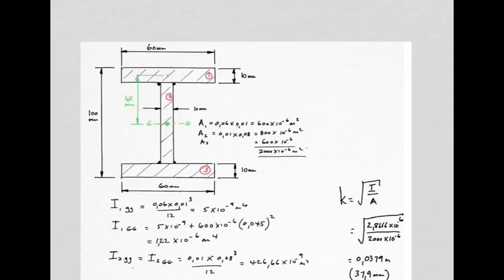Next step is to consider area 1, which is this rectangle as discussed, and determine its second moment of area about an axis passing horizontally through its own centroid. Now its own centroid is going to be denoted with lowercase g's like that. And remember, for a rectangular shape it is BD cubed over 12. Breadth times depth cubed over 12. An easy way to remember it is B is this way in line with the axis that you're dealing with, and D, the one that gets cubed, is perpendicular to the axis that you're dealing with.